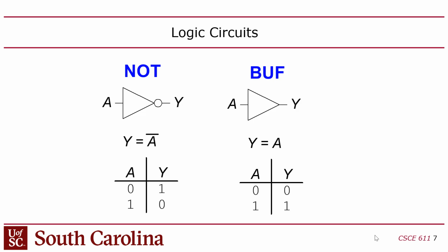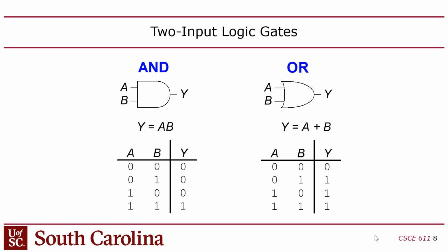But what is a logic gate? Well, a logic gate in and of itself is an abstraction. If you drill down inside the logic gate, then there's other stuff inside there. In an ASIC, there are transistors. And in an FPGA, the logic gates are actually built from LUTs, lookup tables, little memories, essentially. But at the abstraction level of the logic gate, you have these symbols that are connected with lines, and their behavior can be described through the truth table. So then we have an AND gate. You guys remember that? An OR gate, AND gate, they have 2 inputs and 1 output.